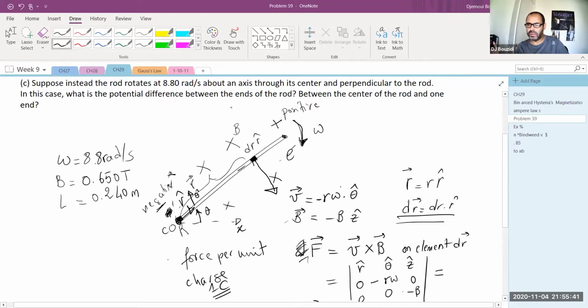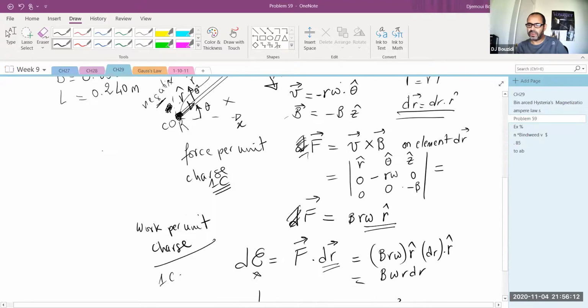It's the same picture. Whether positive charges move from the center of rotation all the way to the end of the other rod, which is fine, okay? But since we know the truth, that it's actually the electrons that move from the end of the rod down to where the center of rotation is, then it's the same net effect, basically. I have an EMF now. It's like I have a battery now that looks like this. And this is the EMF that I was able to calculate.